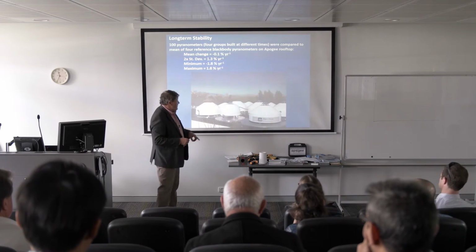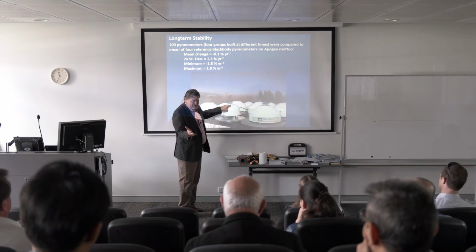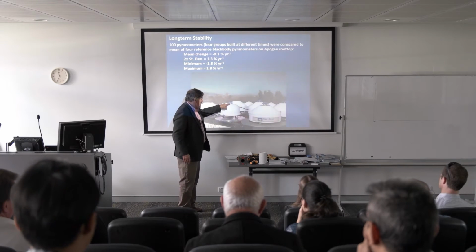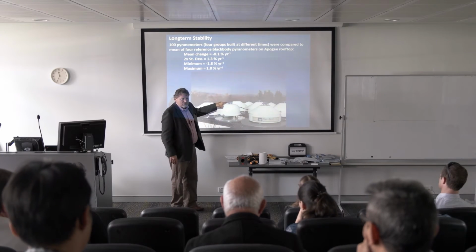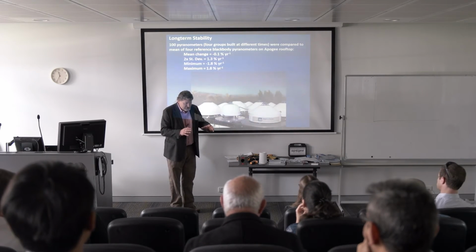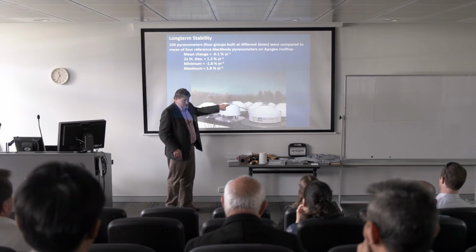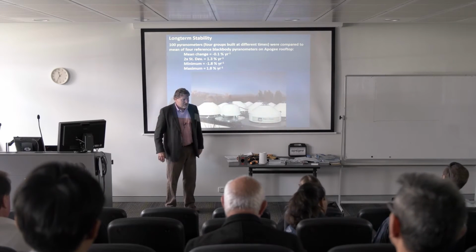In black body pyranometers, it's changes in this black surface. Now, Mark just talked about emissivity. Boy, they work hard to make that emissivity as close to 1.00 as possible, but as that ages, it starts to turn gray. And if it gets from 1.00 to 0.99, well, there's a 1% error.